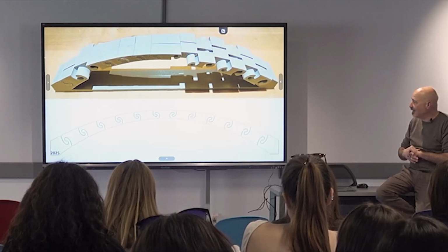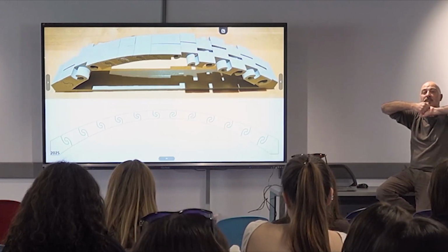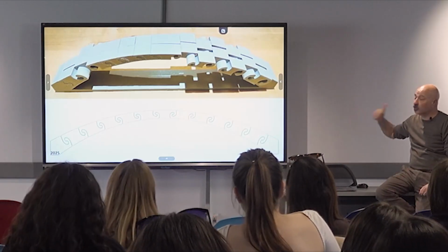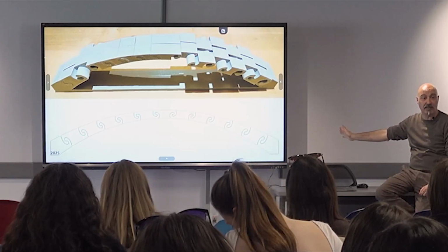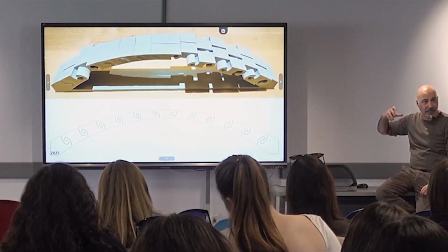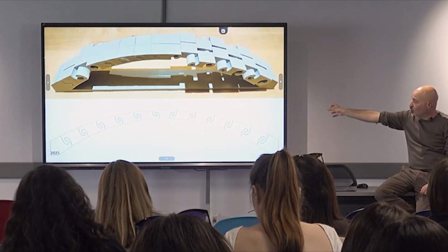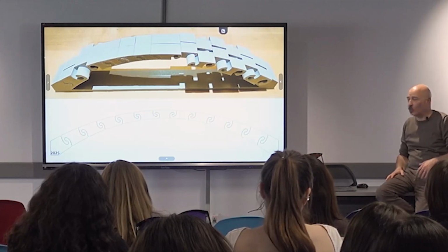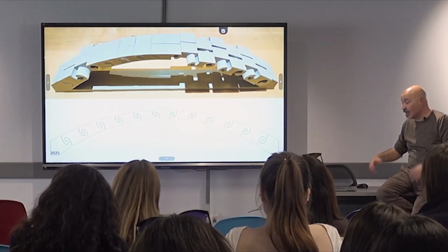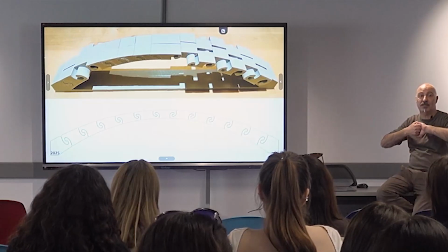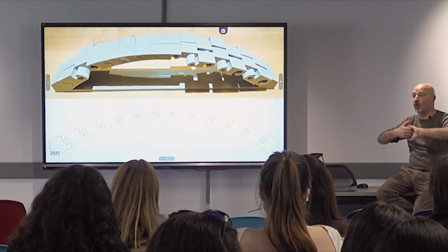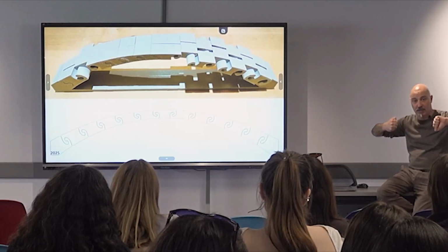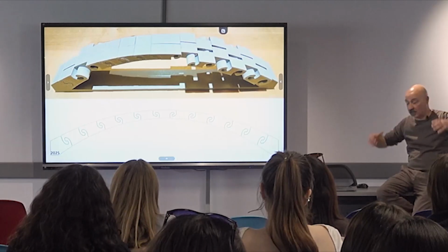It is something linked to the idea to connect together all the ashlars. Why? First of all, to try to avoid using centering, because if we are able to calculate to have each block assembled without centering, we can also not use the center, but we can also make the structural behavior of the vault not only in compression, but also in tension for earthquake situation.